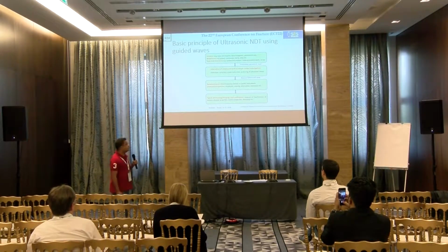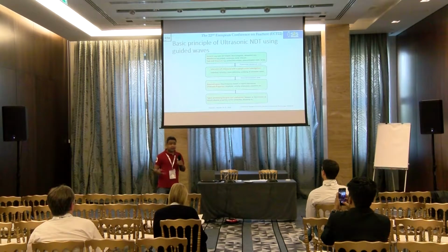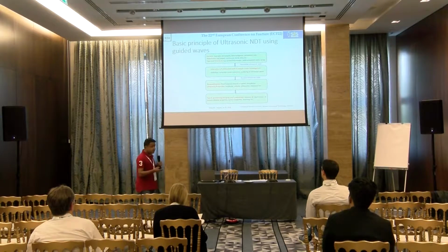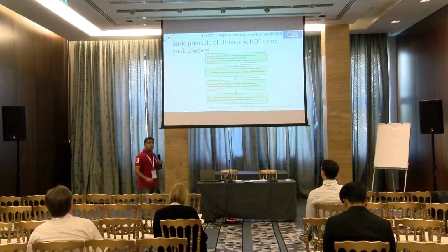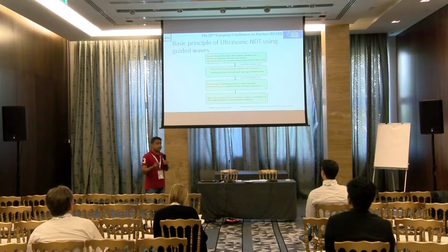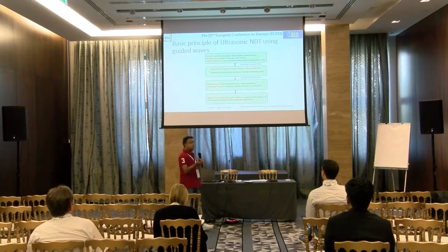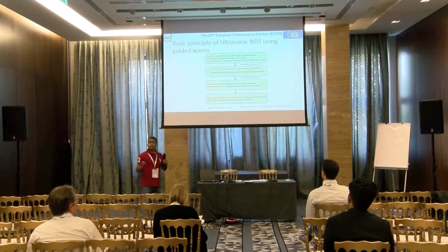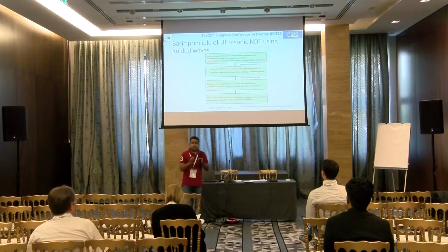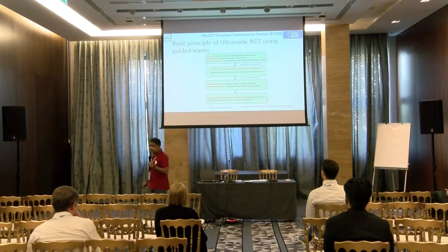Sensor or transducer may be any type. It can be laser, air-coupled, electromagnetic, piezoelectric. It can transmit any waves: pulse, continuous, chirp signal, burst signal. It can work in contact or non-contact manner. A single transducer can be used as a transmitter or receiver, which means pulse echo mode. Or two transducers working as a transmitter and receiver respectively, which is called pitch catch mode. Or many transducers can be connected together to form a phased array.